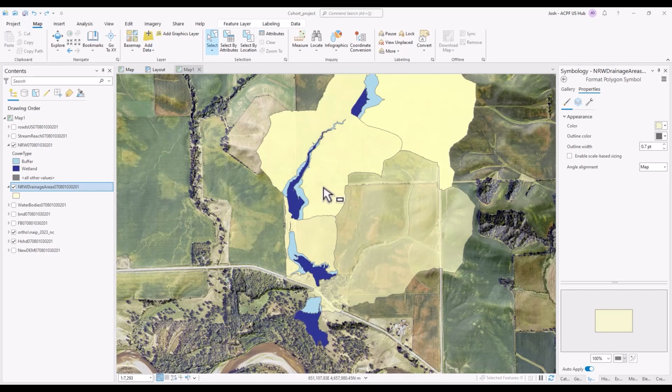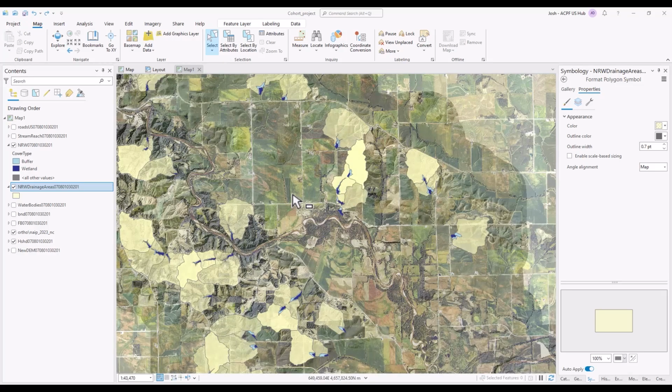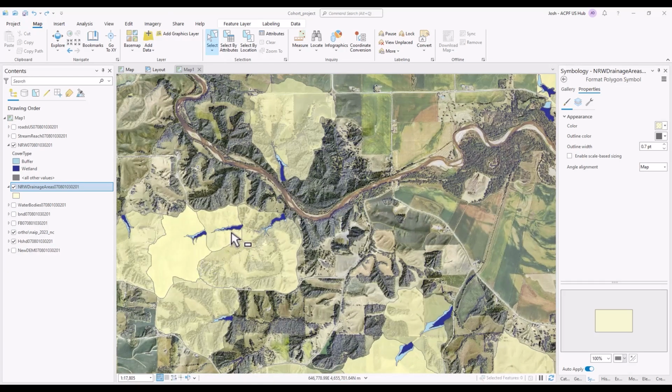In this case, you probably wouldn't build these that are further upstream. You would build the one that's further downstream. That's because the furthest one down is going to treat the same area as the ones upstream. It's just good to be conscious of your outputs. There are a few of these areas in our watershed. Any that are upstream of each other, you would want to prioritize the one downstream first, because it's going to treat all the area that is upstream.